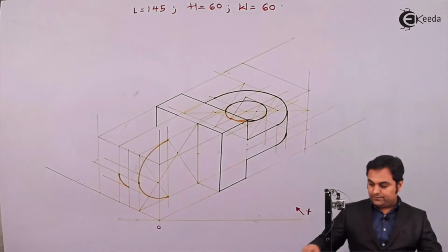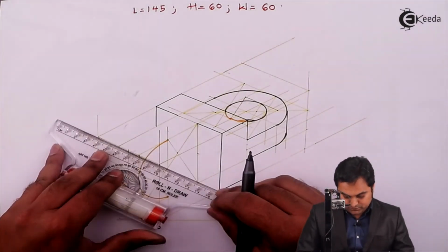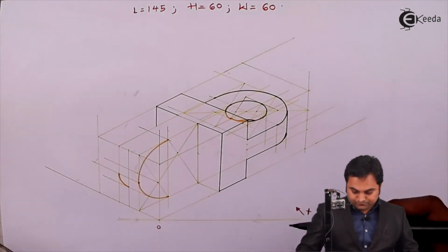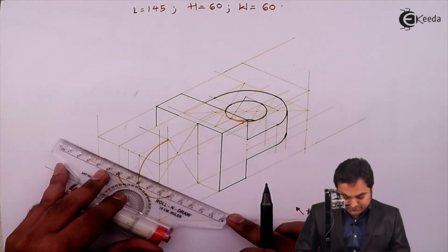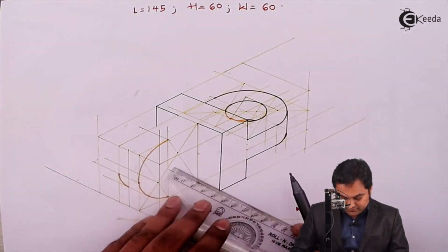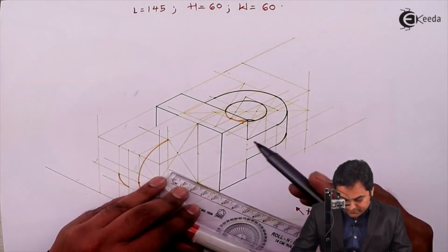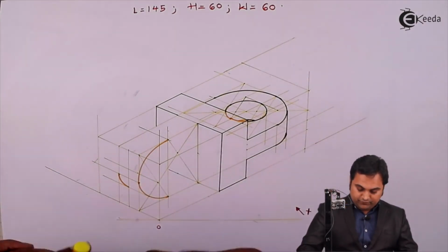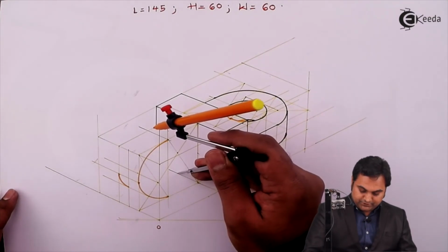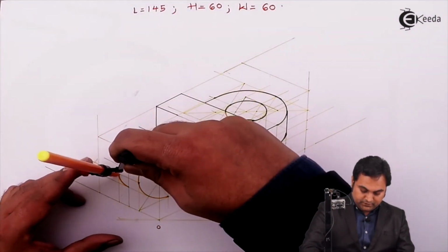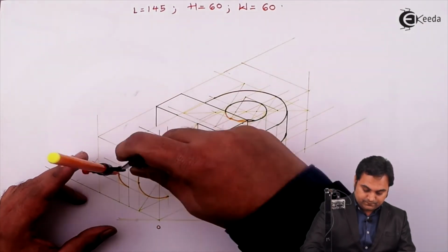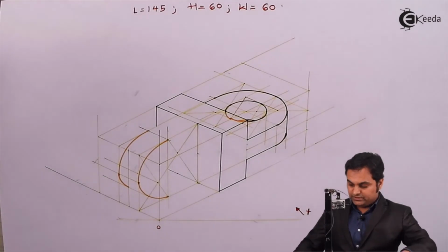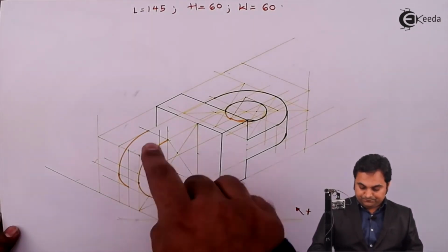Drawing an arc here. Next, through this width, I am drawing a light parallel line. And then the center which I had used. Now this center will be 20 mm behind, as I want the semicircle to be 20 mm behind. Now for that, taking this new center, radius up till the arc where it has ended, extending it over here. Next, joining these arcs with the help of a light line.